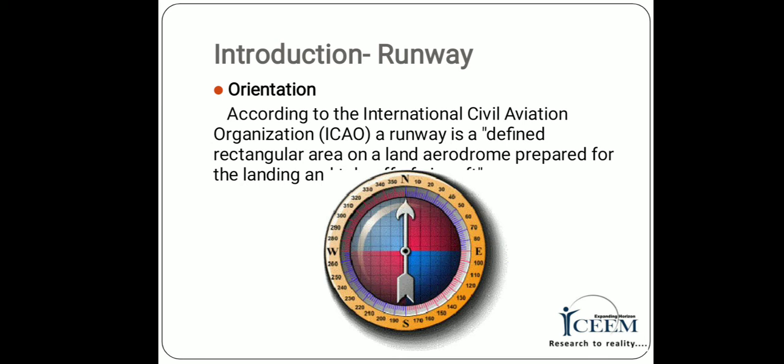During landing, the headwind provides a braking effect and the aircraft comes to a stop in a smaller length of runway. Landing and takeoff operations, if done along the wind direction, would require a longer runway. The challenge for the designer is to accommodate all the aircraft using the facility in a reliable and reasonable manner.